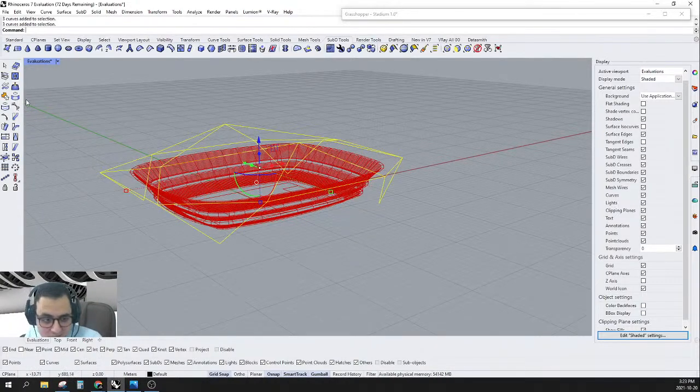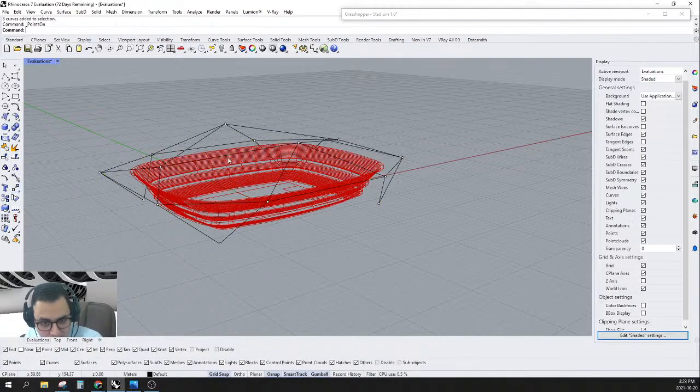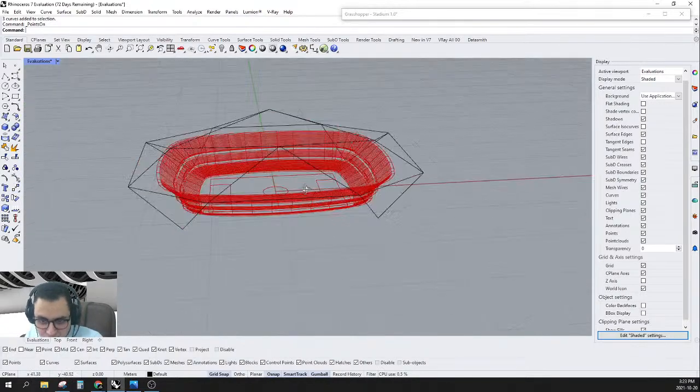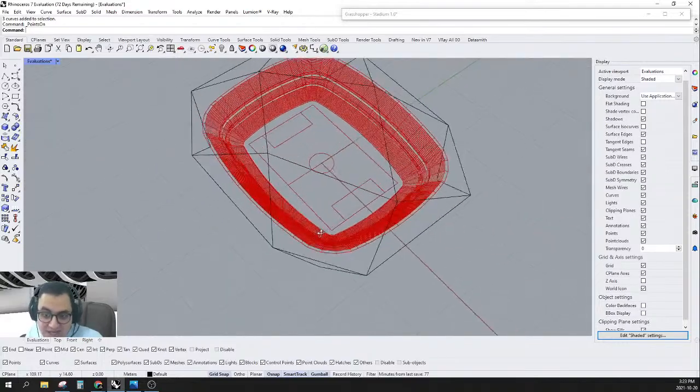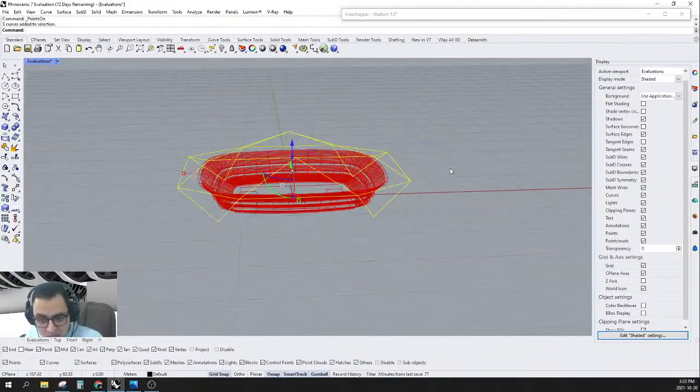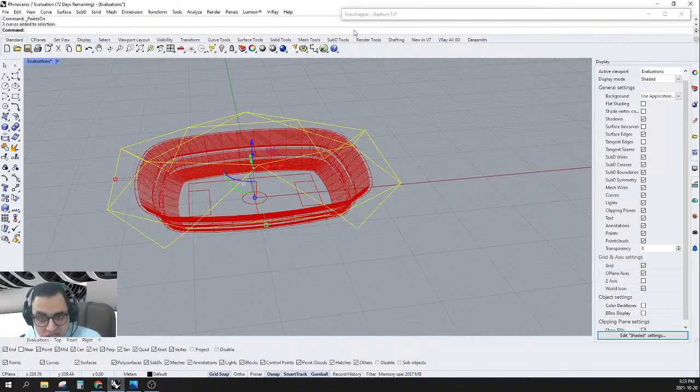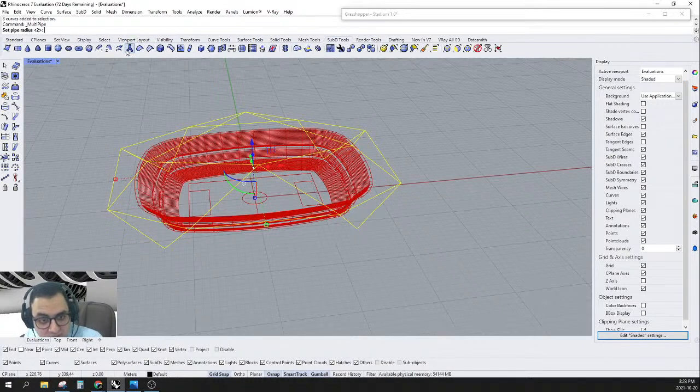And also, while they are grouped, you can edit their control points. But for now, let's make them groups like this, and simply go to again multi sub D multi pipe, and it's 2. The radius is 2. I think the radius was fine. Cap is on or off, it doesn't matter.